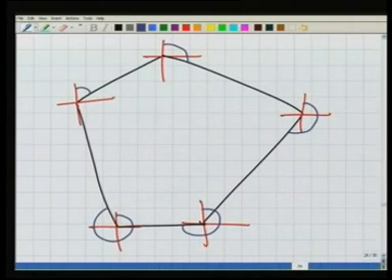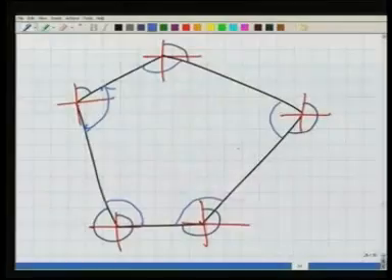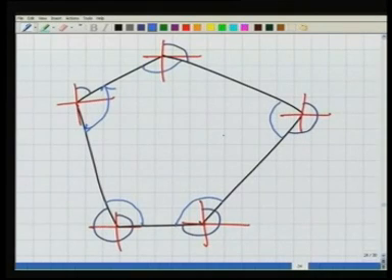You know all these angles. So by knowing these bearings, it is also possible that you can determine these internal angles. I am not going to solve any numerical problem here. Rather, I will advise you to please go through any textbook and solve the numerical problem. It's a very simple problem. If you know the bearings of all the lines, you can determine the internal angles of the traverse. And of course, similarly, vice versa.